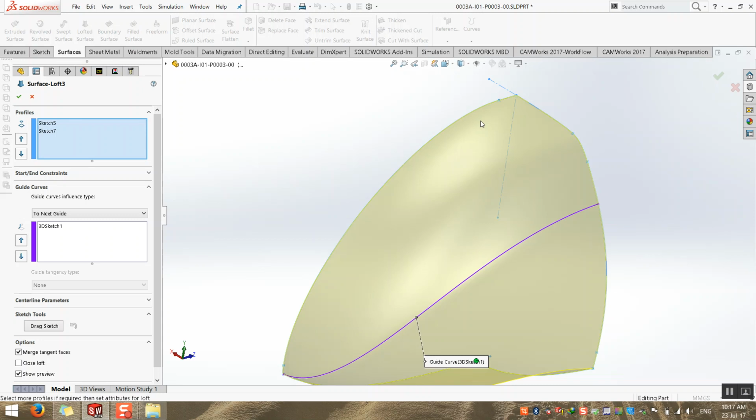This shape and this shape have a loft with this guide. Okay? The surface itself, when you make a loft, you have something called edge condition. Edge condition. What's the edge condition? Edge condition controls the direction of edges at the end of profiles and guides.